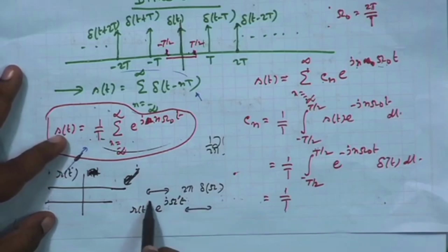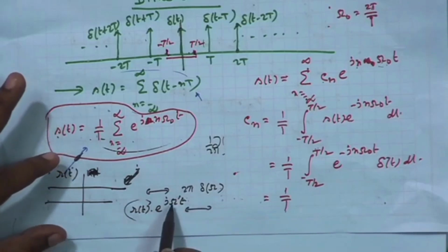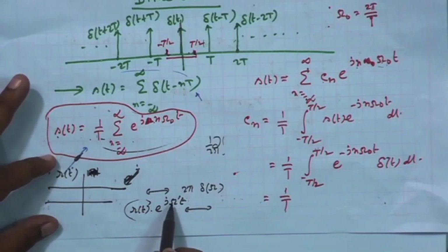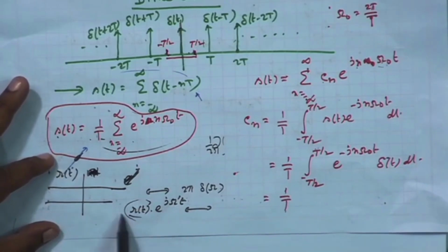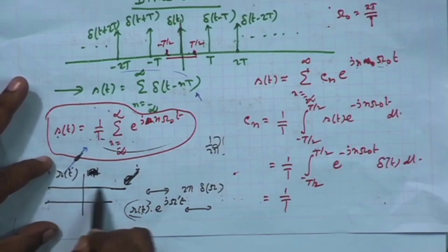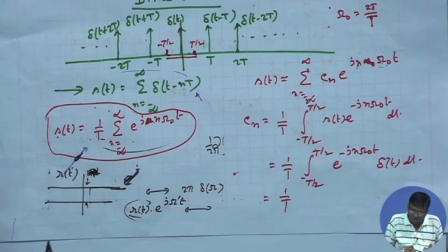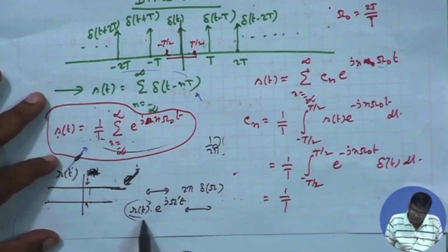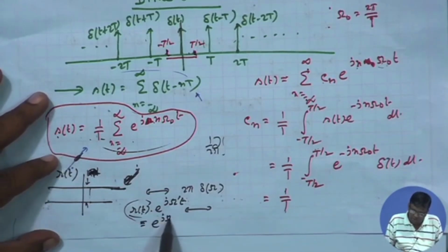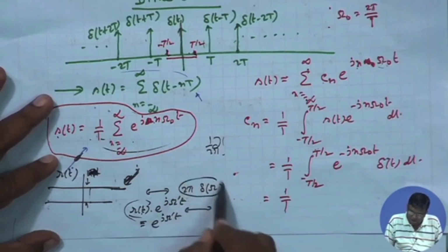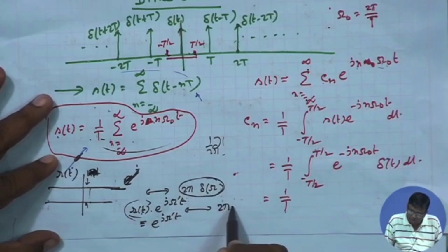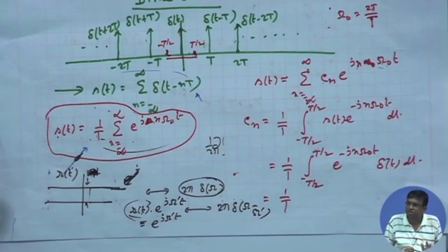It will be the Fourier transform of RT shifted to the right by omega prime. But what is this function? RT is 1 all throughout, a DC function. So, 1 into this is equivalent to this function itself. Its Fourier transform is the original Fourier transform of RT, 2 pi delta, but instead of omega it will be omega minus omega prime. It is shifted.